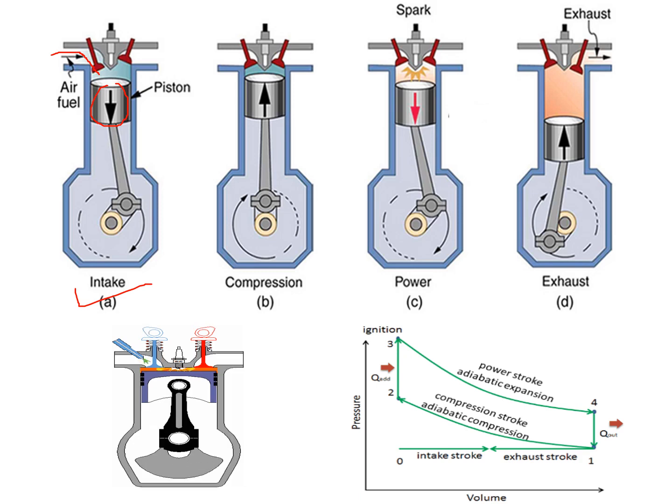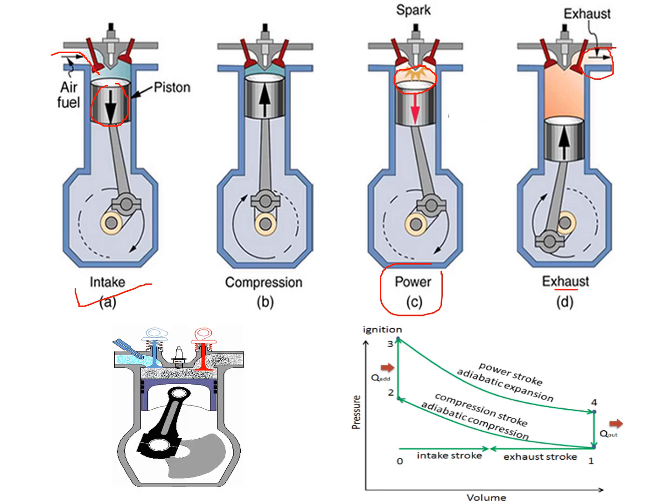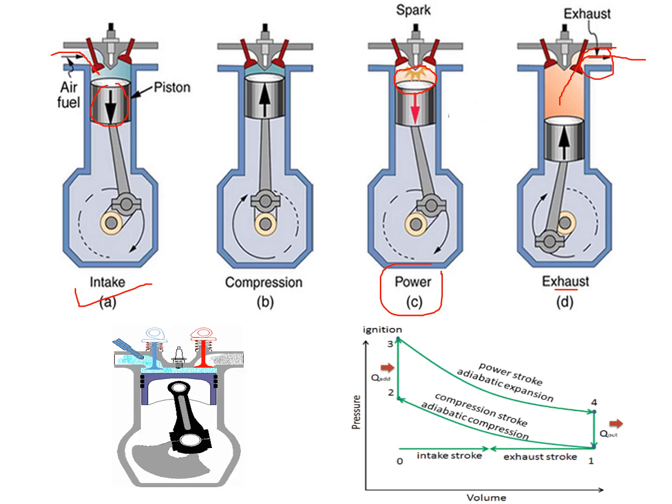Now the piston is moving downward, because a huge force will appear on that particular piston and we are getting the power. So this is the power stroke or the expansion stroke. Now the last one, that is the exhaust stroke. The piston is moving from BDC to TDC. Inlet valve is closed, but the exhaust valve opens, due to which all the burnt gases will escape out to the surroundings. So suction, compression. At the end of the compression we have the combustion, and then we are getting the power during the expansion or power stroke, and then at last we have the exhaust, meaning all the burnt gases escape away. So this is again the cycle.